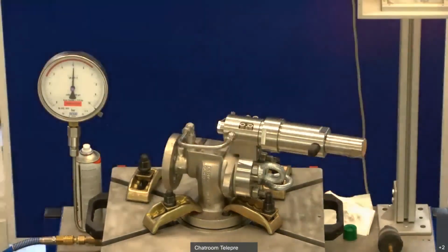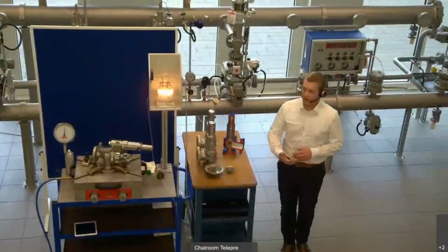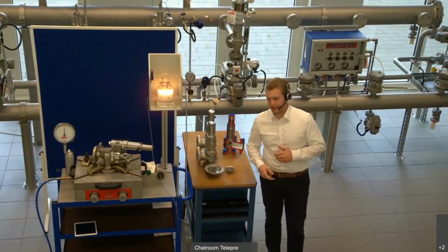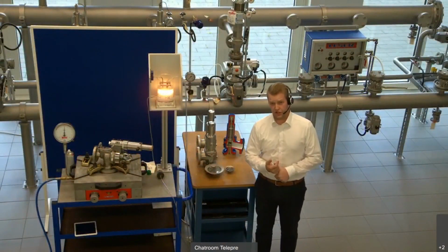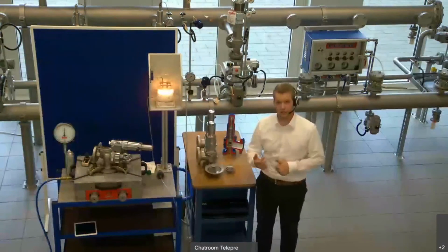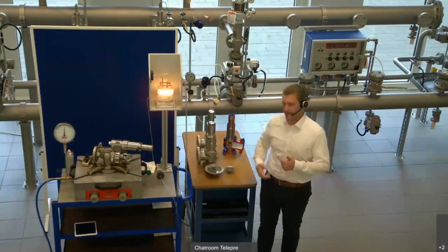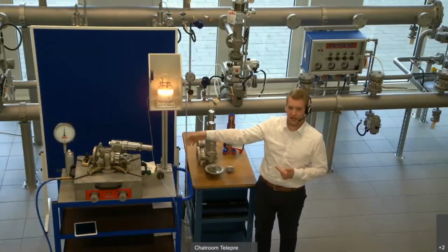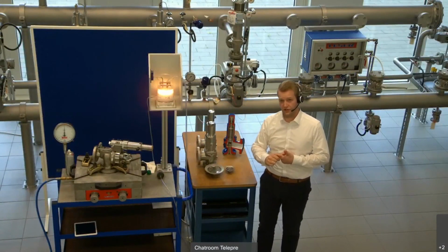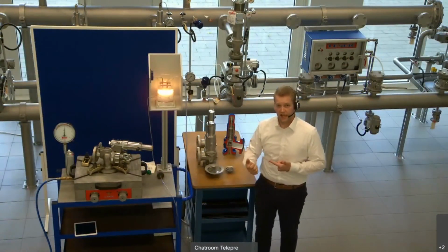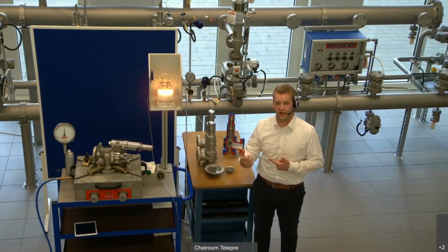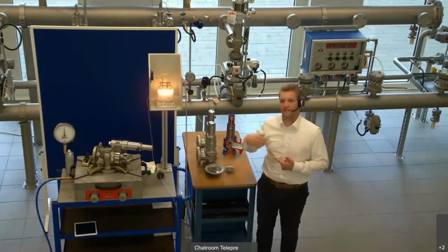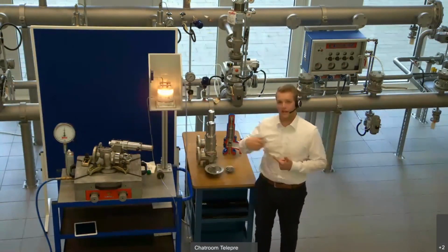This was our Leser training break for today. You learned something about the different definitions of tightness, the body tightness, and this was a test of body tightness. And you learned the other definition of seat tightness. Have a look into the API 527 and the Leser global standard with nano tightness.